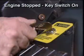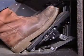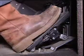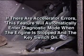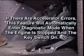With the engine stopped and the key switch on, the operator cycles the accelerator 3 times to enter the diagnostic mode. Once in diagnostic mode, each additional cycling of the accelerator increments to the next fault code. If there are accelerator errors, this feature will automatically enter diagnostic mode when the engine is stopped and the key switch is on.